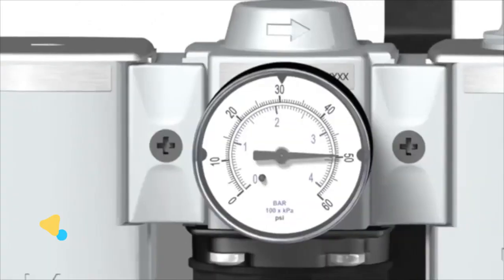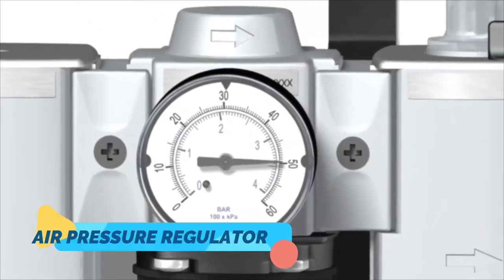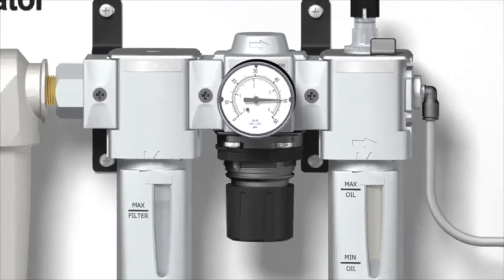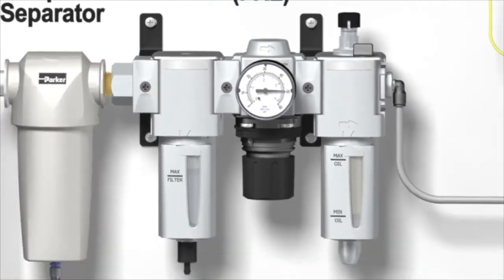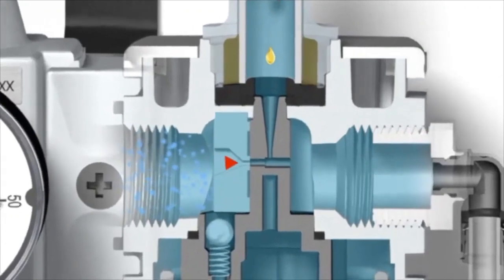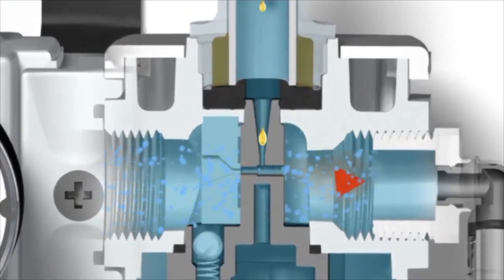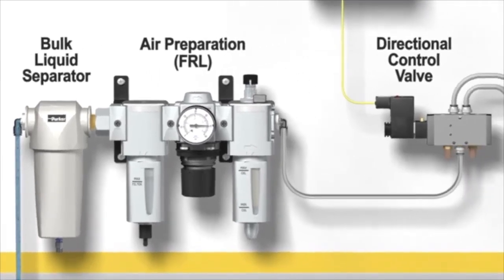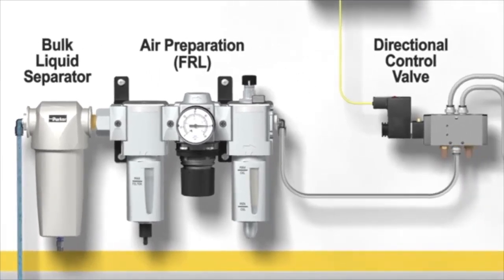Number 6. Air pressure regulators reduce supply pressure to the level required for efficient operation of pneumatic equipment, and they will reduce a supply or inlet pressure to a lower outlet pressure and work to maintain this outlet pressure despite fluctuations in the inlet pressure. The reduction of inlet pressure to a lower outlet pressure is the key characteristic of a pressure regulator.